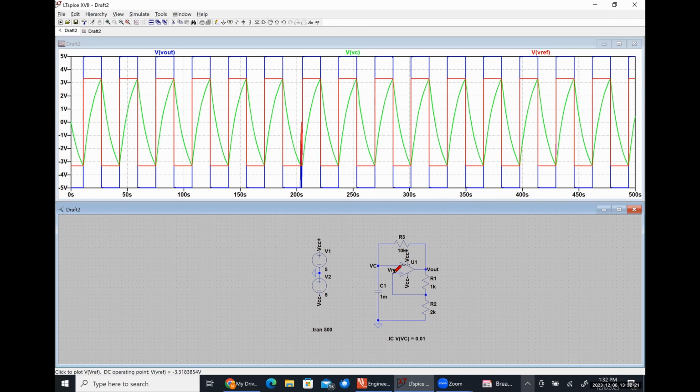So effectively, we can see here that whenever VN is less than V low, the output is going to be 0. This guy right here, VN is 2.5 volts, so that's between V high and V low, and our output is high.